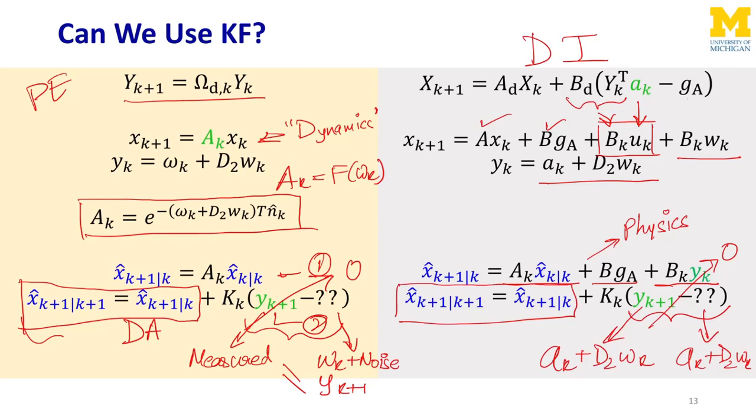which means that the Kalman filter does not affect the model. So the point is, if you're using inertial sensors, just a_k and omega_k measurements, the Kalman filter is not even applicable, because whatever output you want to use in the Kalman filter, you make the output error 0. And when you multiply 0 with anything, you get a 0. So you never get the correction step. You only get the physics update. And there is no data assimilation step when you're doing inertial navigation.